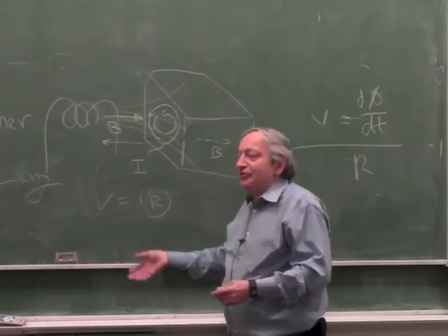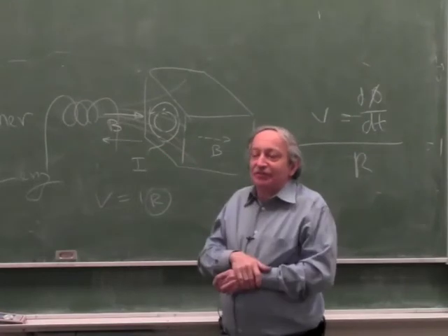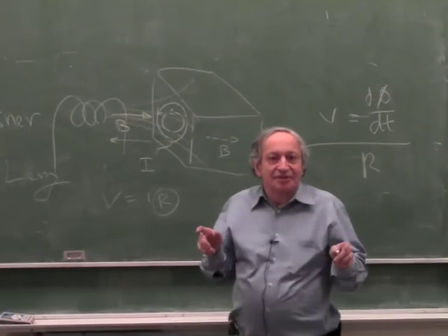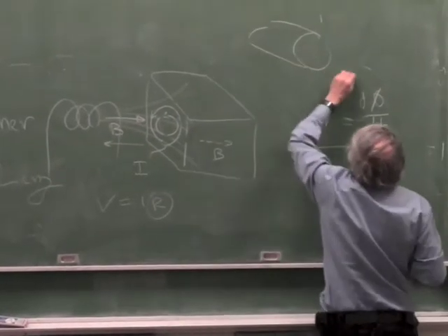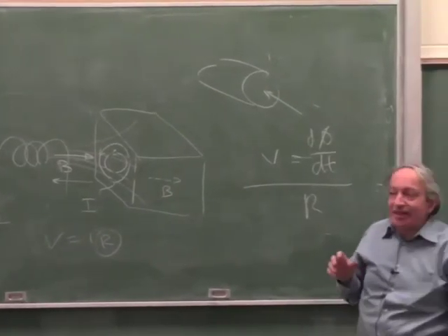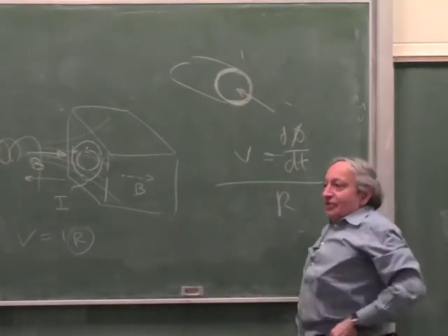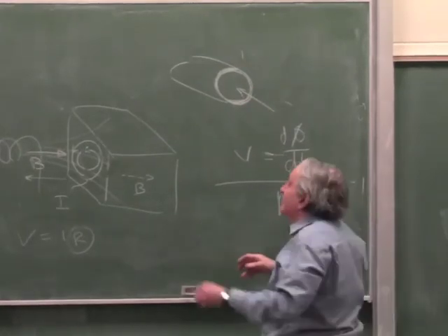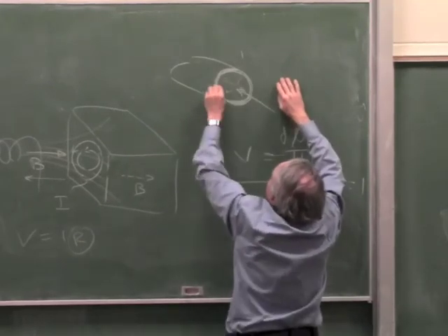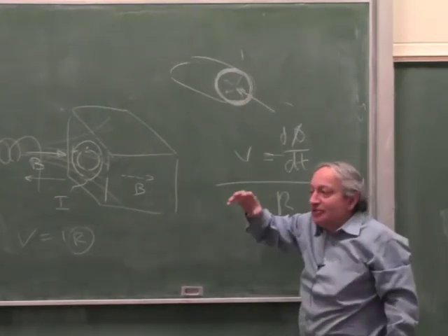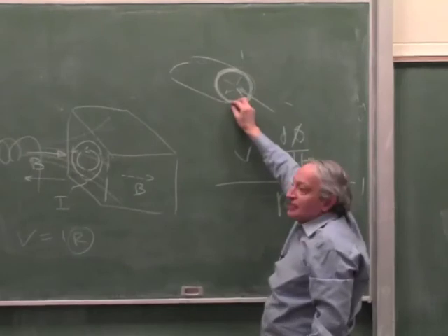If copper is not so good for low frequencies, steel is not good for high frequencies. By the way, the reason steel is not good for high frequencies is another reason called skin effect. Okay, how many people here know what skin effect is? Okay, more of you should know. When you run a current through a conductor at low frequency, the whole cross section carries the current. At high frequency, the current is only sitting on the outside and cannot penetrate inside the conductor. So if the conductor was hollow or solid, it'll be the same, because the current inside is repelled by itself to the outside. So basically all the current is repelled and it's only sitting on the skin. Now this effect gets stronger and stronger with high frequency, and at very high frequency the conductor is not good because the penetration of the current is very shallow.